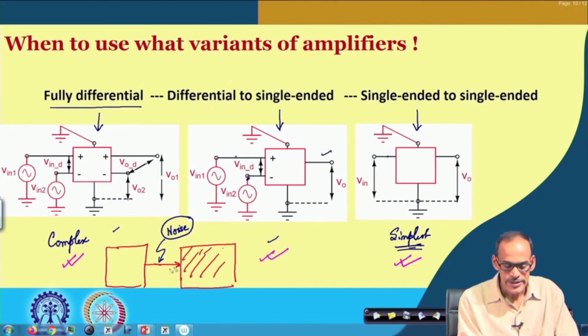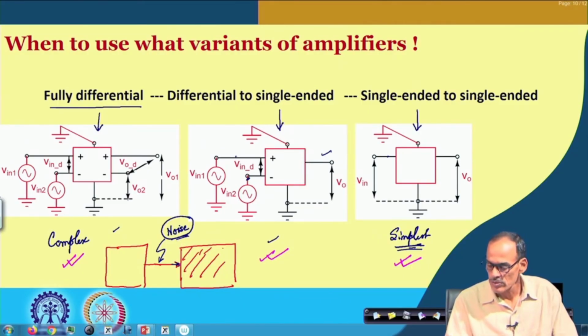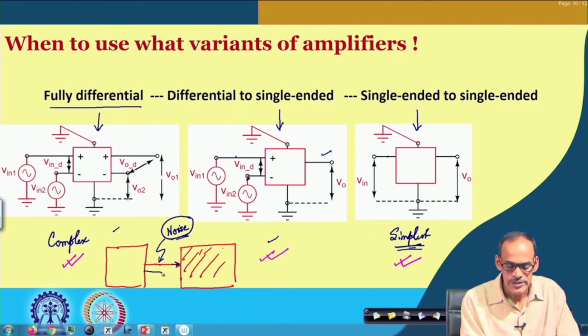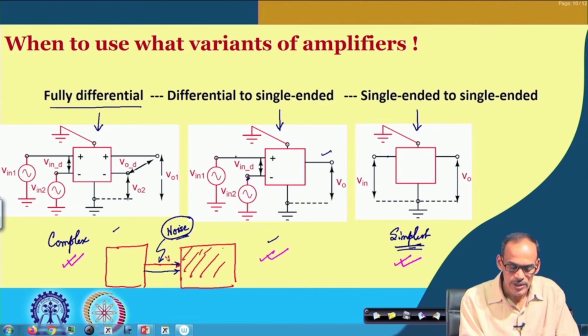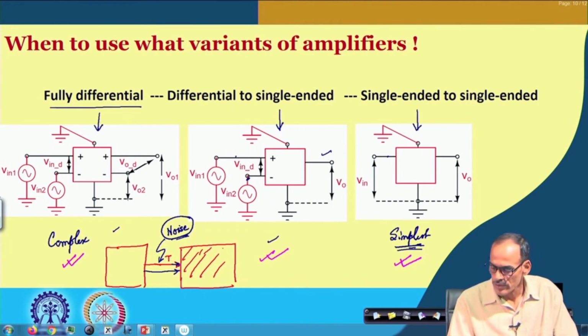So, for such cases, whenever the signal is coming with some interference and this noise is really alarming, we prefer to use differential signaling here, having a true signal path, and along with that we have a complementary signal.